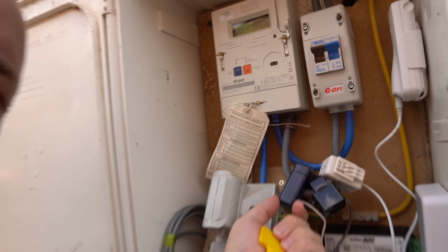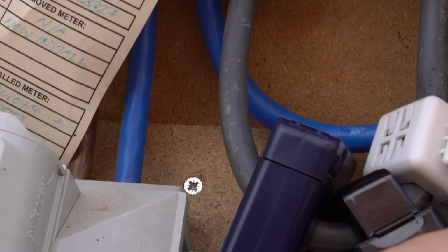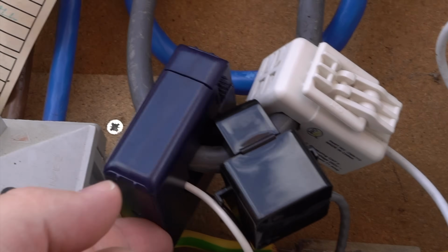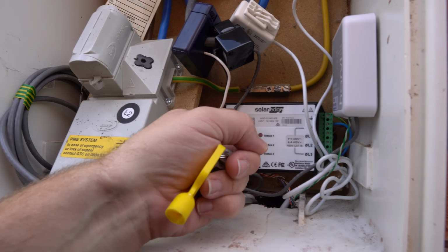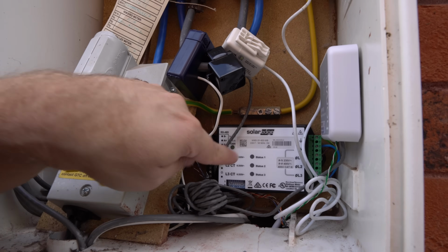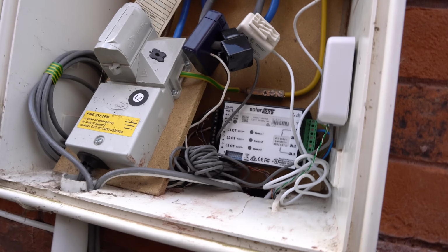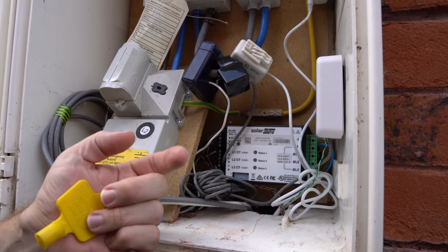Okay, and in here, this is the CT clamp that I spoke about. If you compare this to the hour one, the hour ones aren't directional, whereas these ones are, and just look generally a bit more sturdy. And then here is the Modbus meter. There's a green flashing light here for communication, so that shows that it's communicating back to the inverter itself. This supports up to 3-phase.